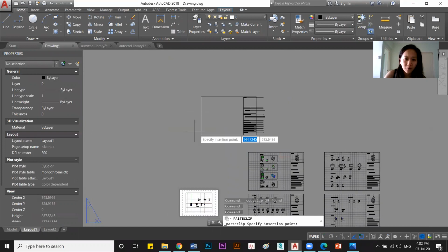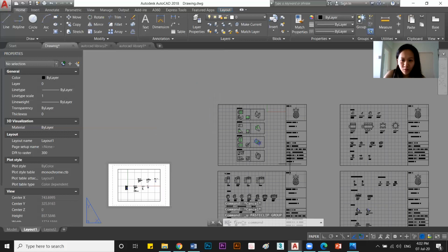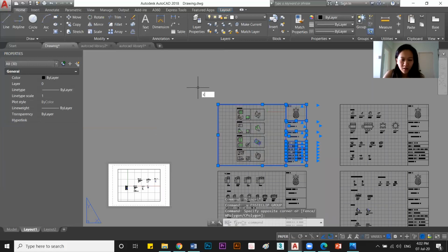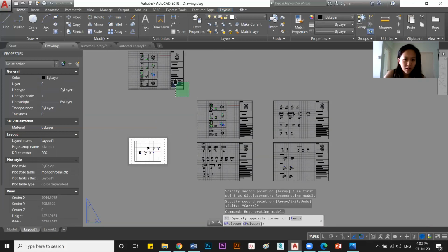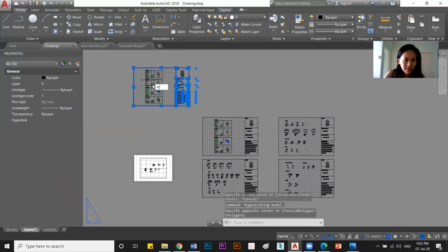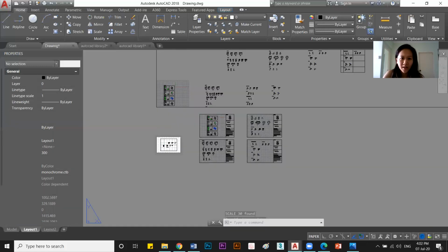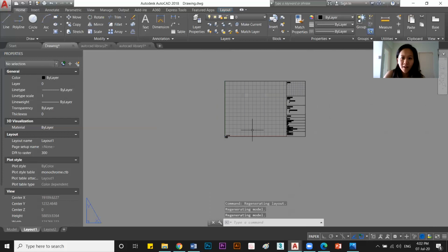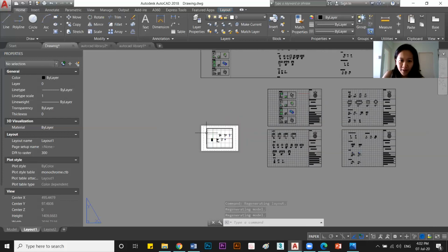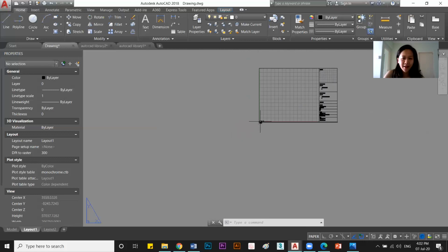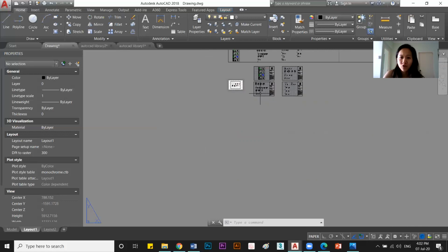what if your title block is very big, right? Oh, sorry, undo, copy this, CO, copy. Some of your, okay, let me see scale SC, let's say 100. Some of your drawing is so big, and then the window is so small. It's okay, never mind. As long as your drawing is following the A3 size.